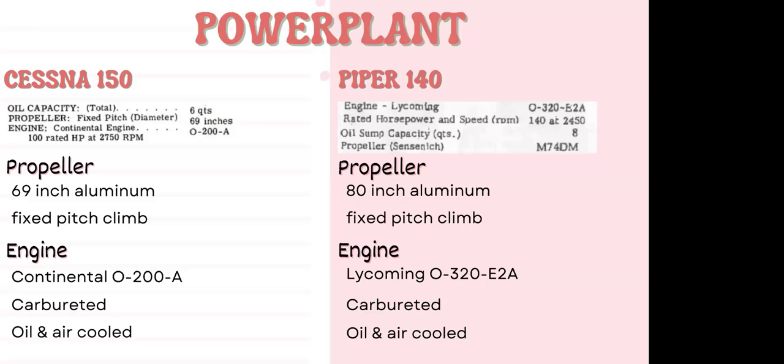And another reason for that is also because of the purpose of the aircraft. There's no reason that we couldn't put a cruise propeller on Bluebell, but if we think about most of the training that we do, it's really pattern work. And so it's going to be more advantageous for us to get that climb performance, especially because we are slightly underpowered, than to get cruise performance, because we're doing most of our training in a climb descent setting.